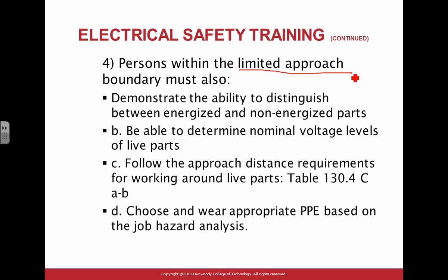You are working on a controlled part of a circuit, a PLC. You're programming a PLC. And inside the box is also a 60 amp 3-phase 480 feeder coming to that piece of equipment, and you are in the same panel. So you're exposed to the same hazard from an arc flash hazard. And I know they have a lot of insulation. They insulate typically, unless they're in a completely different enclosure. If they're in the same enclosure, you're exposed to the same hazard, unless that incoming circuit is in a different enclosure.